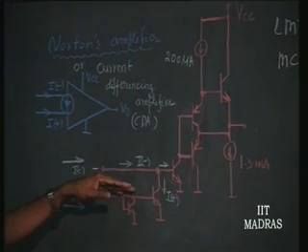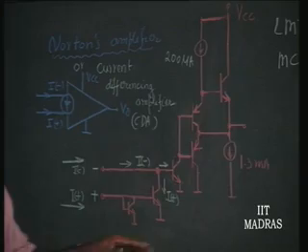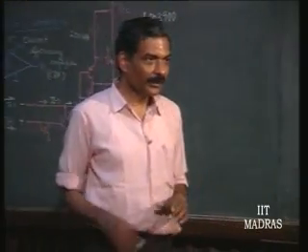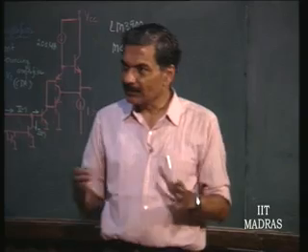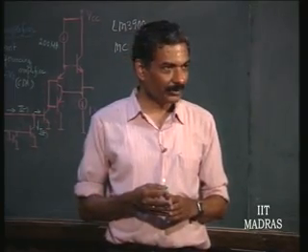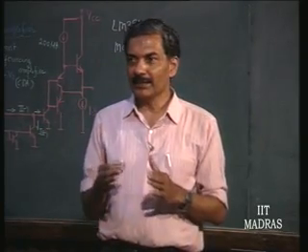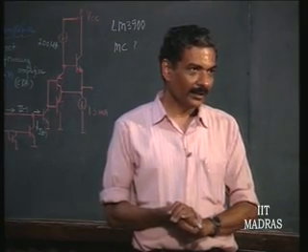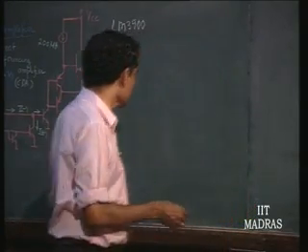And also, you know at what DC potential this is going to be, right. Strategically, you can find out that this DC potential is always going to be one diode drop above the ground potential. All that is known to you at the input. So, it is very easy for normal design of this circuit in a negative feedback environment. Just typically, let us see.